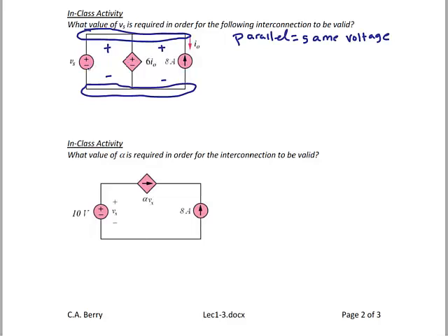So for the first two elements, which are both voltage sources, the second one is a current-controlled voltage source. In order to find the value of that voltage source, we need to go find the controlling variable I0. I0 is the current in that final element, the 8 amps. However, since I0 points down and the 8 amps points up, it's negative 8 amps. If they were pointing the same direction, I0 would equal 8 amps.